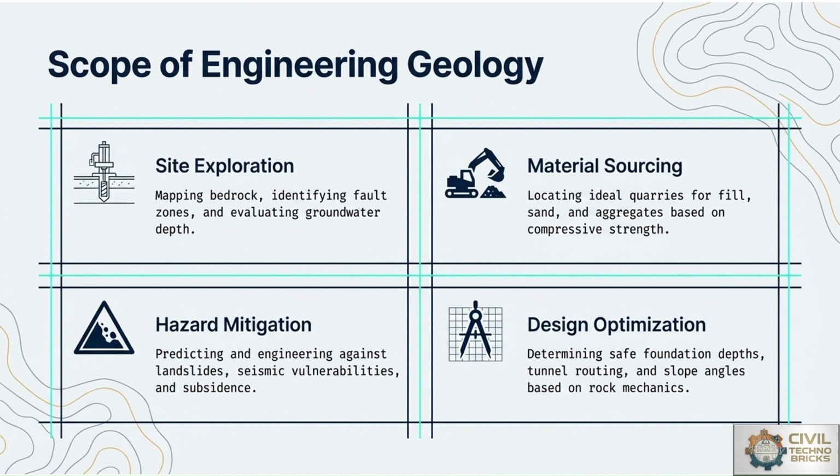Owing to the scope of engineering geology: site selection, site exploration, material sourcing, hazard mitigation, and design optimization are the various domains which are important to be focused on. Site exploration helps to determine subsurface geological conditions before construction, like mapping of bedrock, identifying fault zones, and evaluating groundwater depth. Second, material sourcing, which identifies suitable rocks, aggregates, and soil for engineering works, where these parameters are most important to check on the basis of compressive strength.